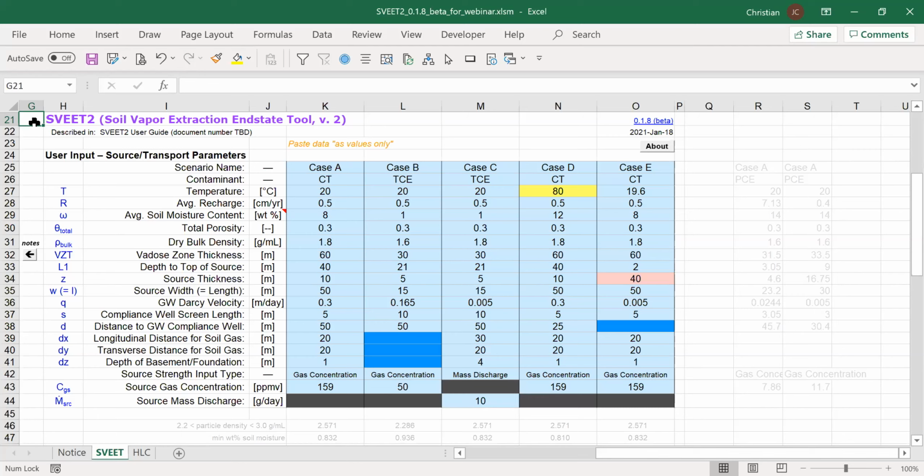But essentially, you could have a NAPL in the vadose zone. At Hanford, the situation was where they disposed an aqueous waste with carbon tetrachloride, and there was a fine grain zone, and carbon tet hung up in that fine grain zone and acted as a source. So either scenario like that would be appropriate. If the NAPL were continuing to migrate, you'd have to consider that long term. So it depends on where that's at in the vadose zone and migration.